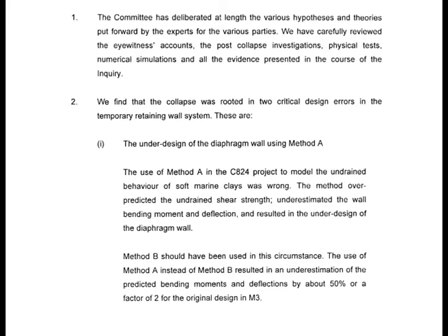it contains some very nice information on the project, why it failed, how the project was managed and what led to the failure. But here I captured the gist of the finding. And the gist of the finding was that the collapse was rooted in two critical design errors in a temporary retaining wall system. The first is related to a geotechnical issue. The second is a structural issue. It's actually the strut to waler connection. So I won't bother with the second one,